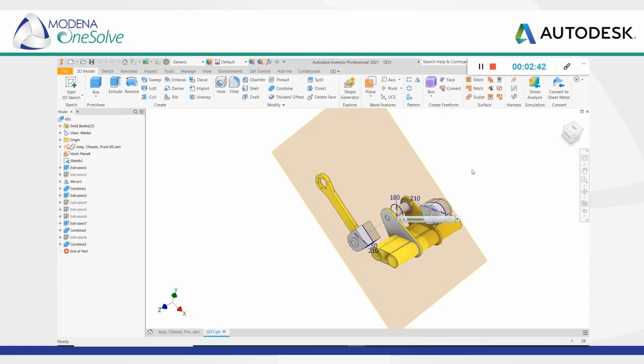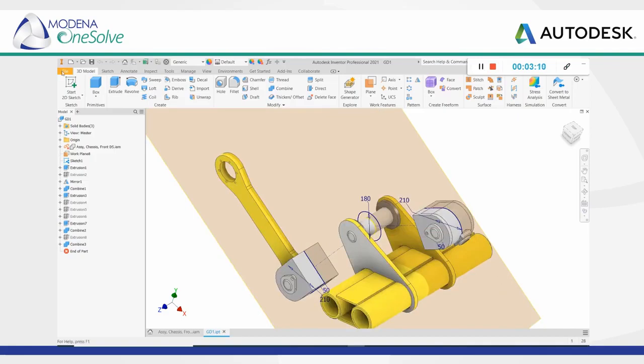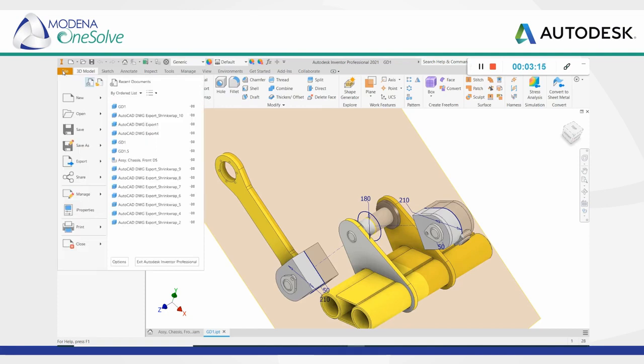Now at this stage, we want to get this information into Fusion 360 so we can start the generative design process. There's a couple ways of doing it. You can simply use import and export of the file. So export the file from one application to the other, so from Inventor to Fusion. Or alternatively, we can use Fusion Teams. So what Fusion Teams is going to allow us to do is store this information onto the cloud that both Inventor and Fusion have access to. So there's live data transferring going on here. So what I'm going to do is save this part onto the cloud using my Fusion desktop connector.